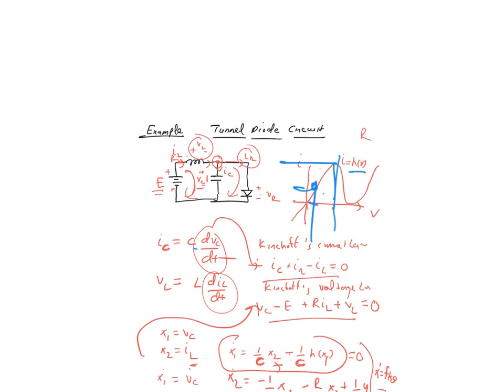also in the next class, where basically we want to analyze smaller systems, second order systems, first. Again, linearization is still a good approximate tool in nonlinear systems as well. It gives you the behavior, at least near the equilibrium point, of these systems. And then we will be doing some phase plots, drawing pictures instead of exactly solving.